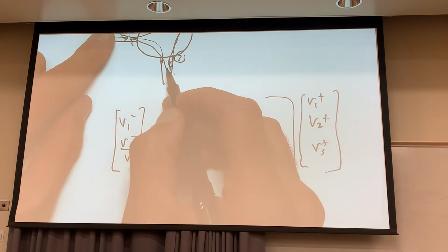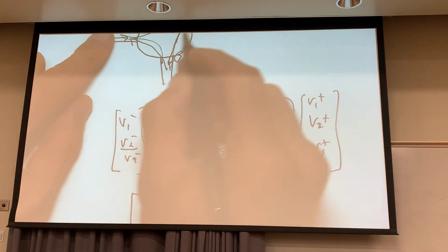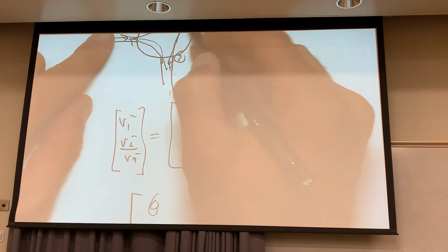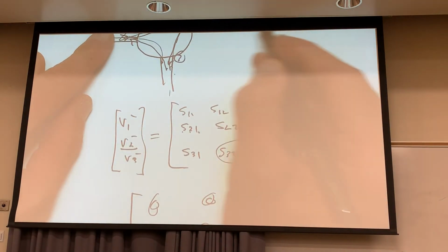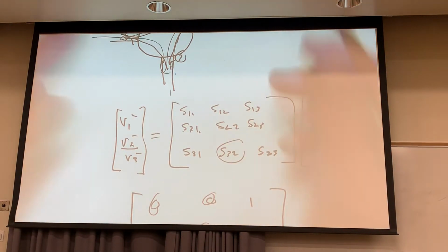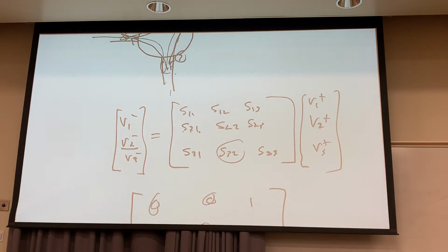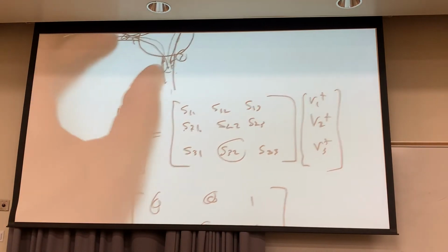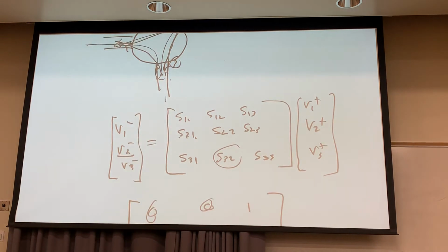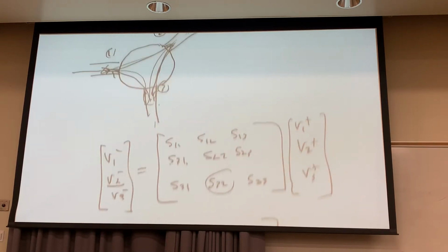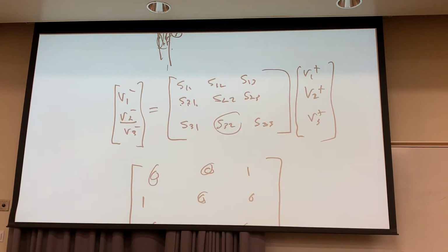The other thing is, when the incoming signal comes back, it does no good if it goes this way. They want all the power to go that way. I'm speaking just from a radar perspective. And to be honest with you, this part right here, the 1-3 coupling, I don't care about in radar. I only care about my signal going out one way, and anything coming back from the antenna goes the other way for training. But for other work, they probably will have an application for that. I don't. And I could see in a bistatic radar that there might be an application for that. But that's a circulator in a nutshell.